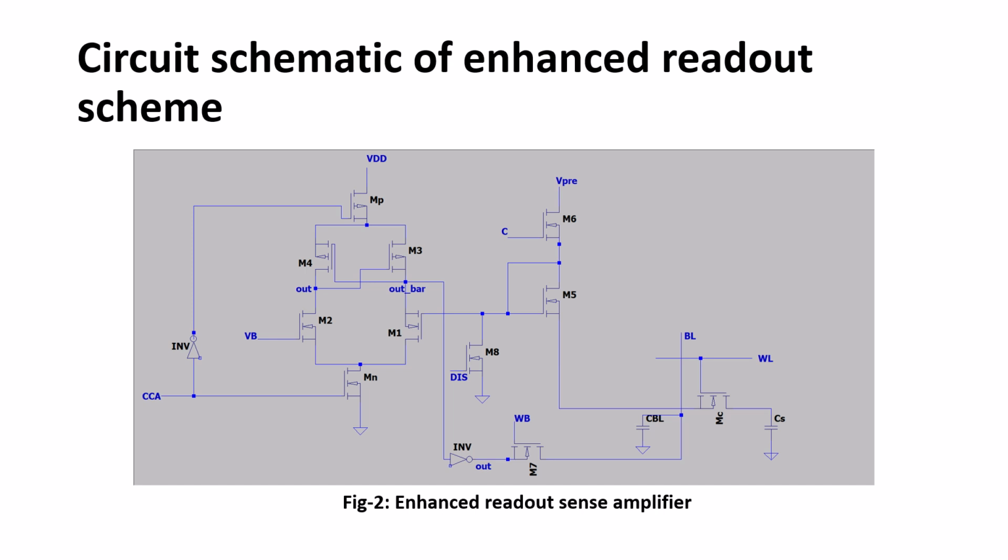Let us have a feel for this, assuming some values. If it has some 650 millivolt and the voltage developed over here is some 670 millivolt, this overdrive voltage is greater than this overdrive voltage. As this is biased previously, the current through this transistor is already defined, which we call the reference current.